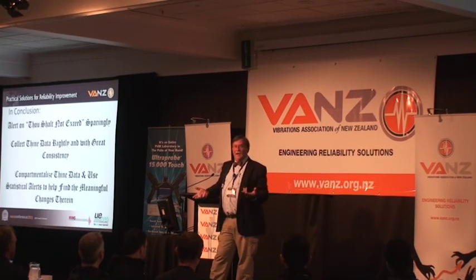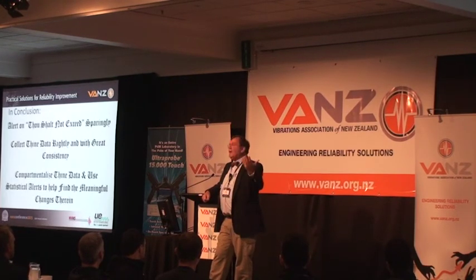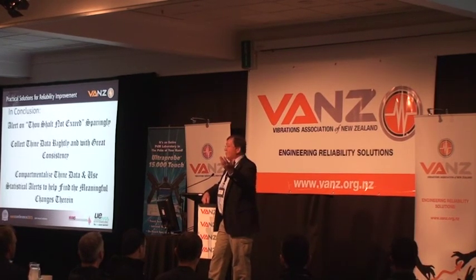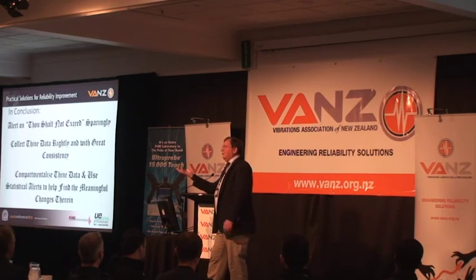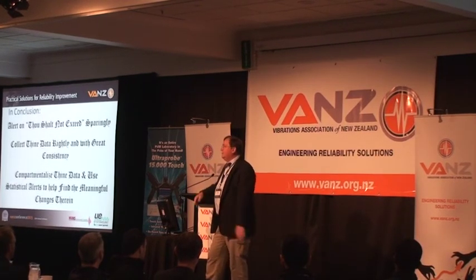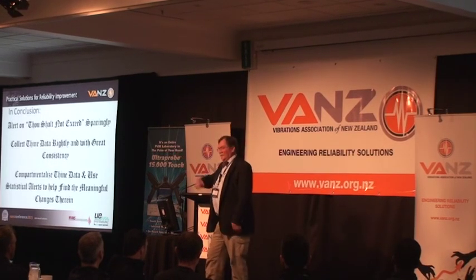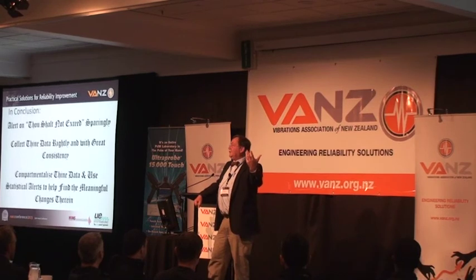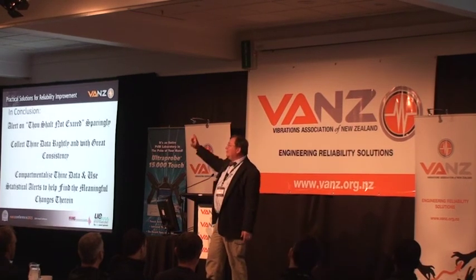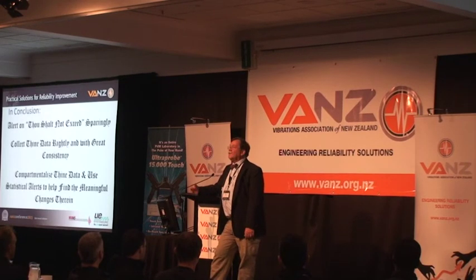And this is where plant management really went nuts on the lube oil guy, because all of a sudden, the viscosity of the initial sample that was good was this, and the viscosity is now that. And you start looking at some of the other parameters in the oil, clearly this is not the same stuff as this, because it had been diluted with the wrong stuff going back into it. And that's actually what led to the problem.